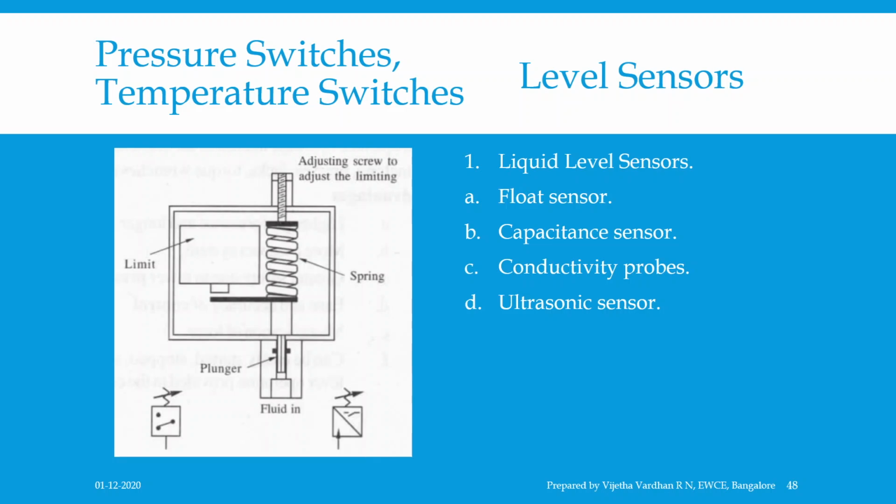The distance between the transducer and the surface of the liquid medium can be calculated based on the time elapsed between emission and return, given the speed of sound. The distance is subtracted from the total tank or vessel depth, and thus liquid levels are accurately calculated.